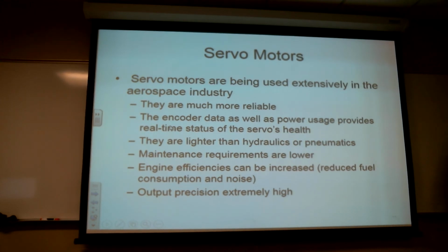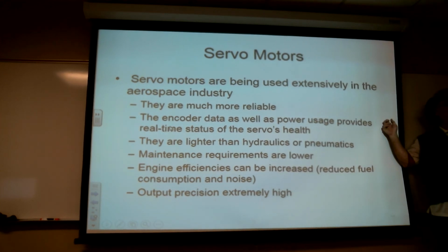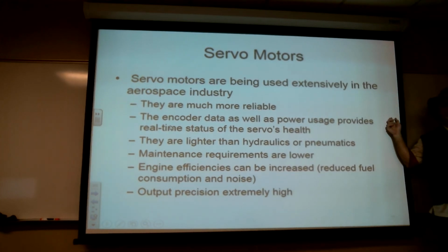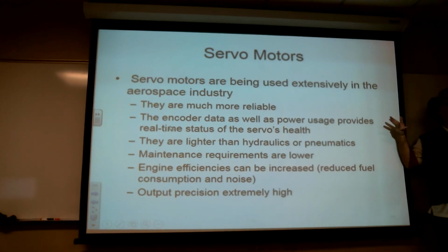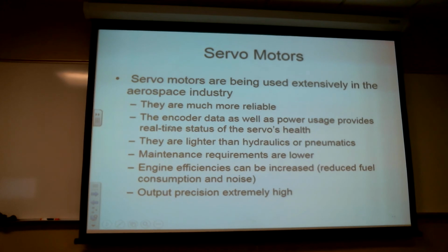And actually, truthfully, if I'm using a networked system, I don't even need that many wires. I just make network A, network B, and network C, and they're all listening to all three. I might have some digital strategies like a heartbeat and a few other signifying data sets that tell all the different components that everybody's good, everybody's doing the right thing.